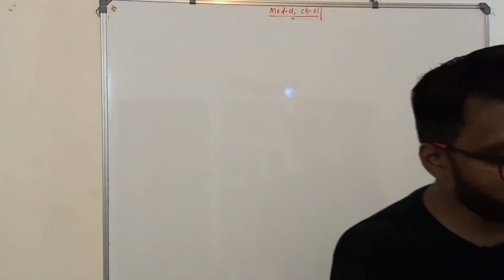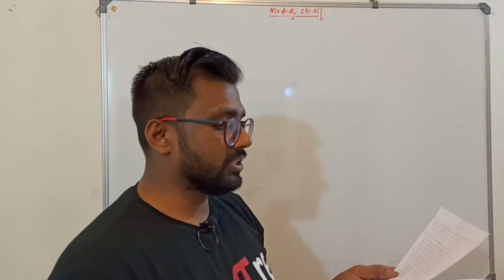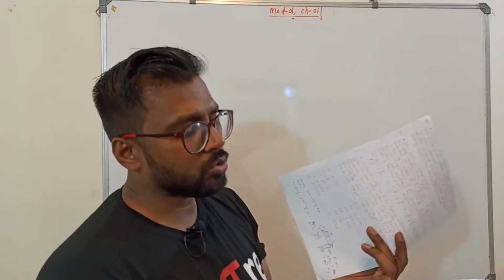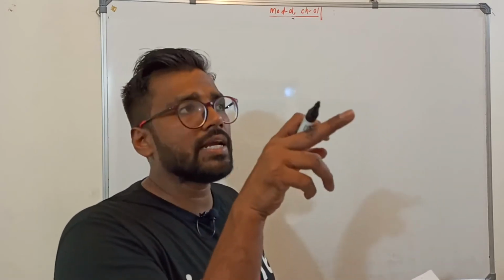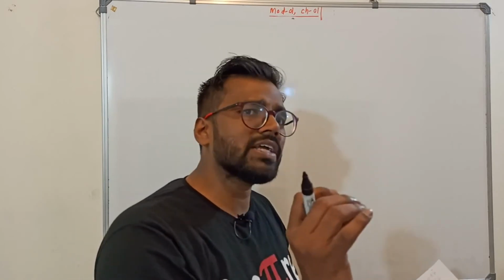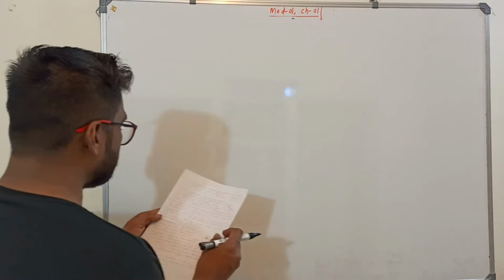Okay, so the next problem we are going to solve is your question number 5. Again, tricky. Soap bubble problems are always tricky. The trickiest part is people forget that there are two contact areas. One, the air trapped and the film. Second, the film and the air outside. So there are two areas, but people always forget and simply write one area, and they make a mistake.